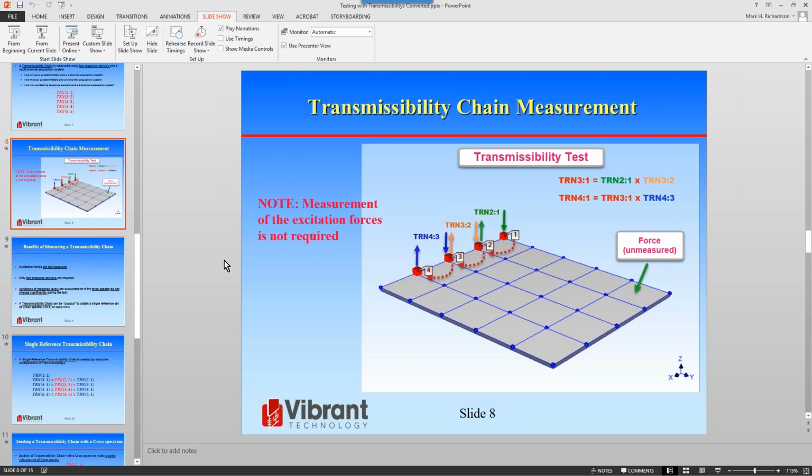I'm going to go along with 2 accelerometers and a 2-channel analyzer making these measurements. So you can see transmissibility 2/1 here is simply defining the first accelerometer as an input, so that it'll be a denominator term or a reference. The second accelerometer is the output, and again I'm using MEscope lingo here, input versus output.